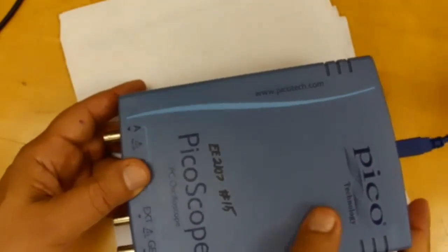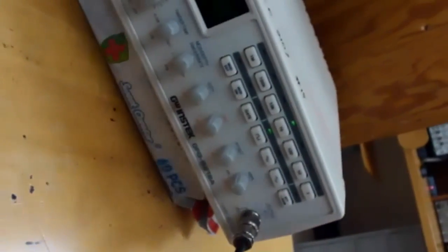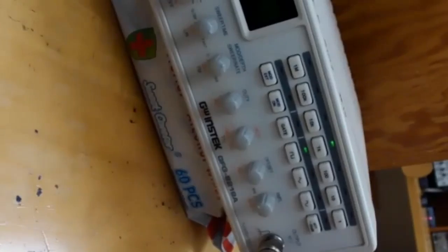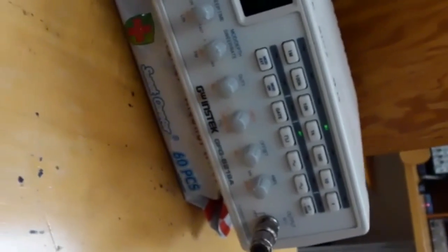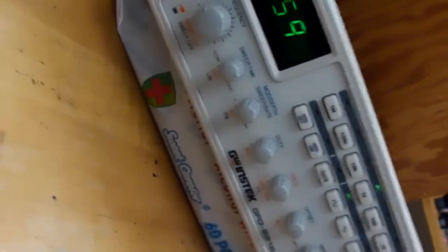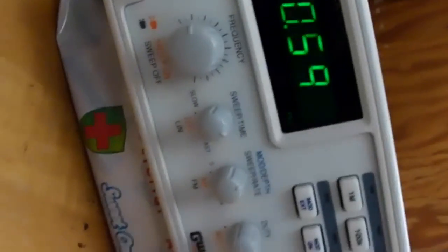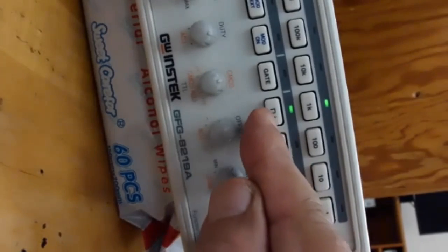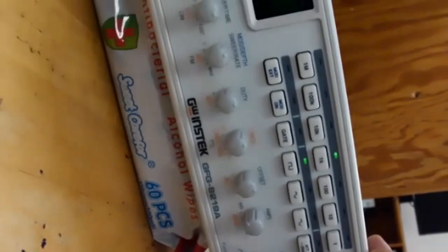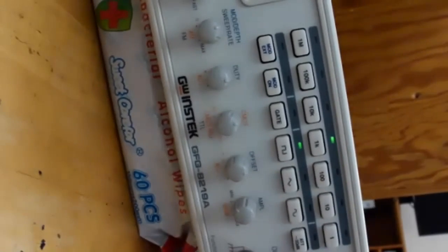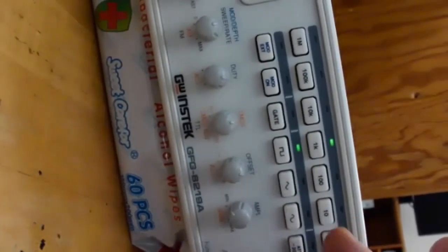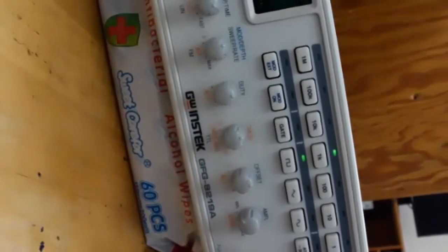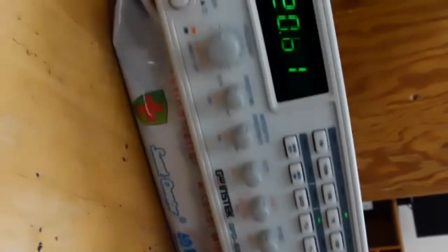I already set up the function generator as I explained in the last video. I did the settings: square wave, and the frequency about 120 hertz. If I get closer to it, let me move it here. That's 120 hertz, right? And you see the green light here. That's the square wave, and that is the range. And the amplitude, you don't know the amplitude, you've got to measure it. So I just move it clockwise and clockwise till I get the right thing. And the cable is connected, as you see here.